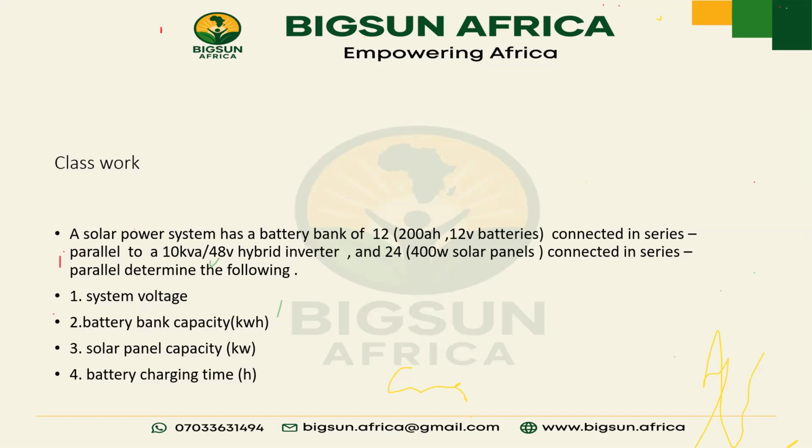So in this case now, what is going to be our system voltage? 48, because the inverter is 10 kVA, 48 volts, right? Then our battery bank capacity, we have gotten it, which is 28.8, right? I hope everybody is getting this together as we are doing it. Okay, good. So our solar panel capacity, we have gotten 9.6.